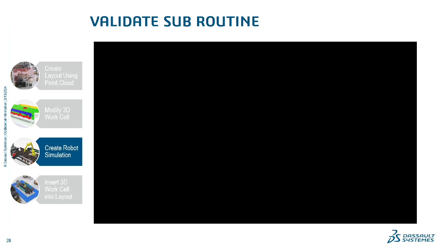Very similar routine can be used for rail equipment. So if you have a long rail, you can use the compute rail values and it'll say where your robot should be to execute each step of its routine.